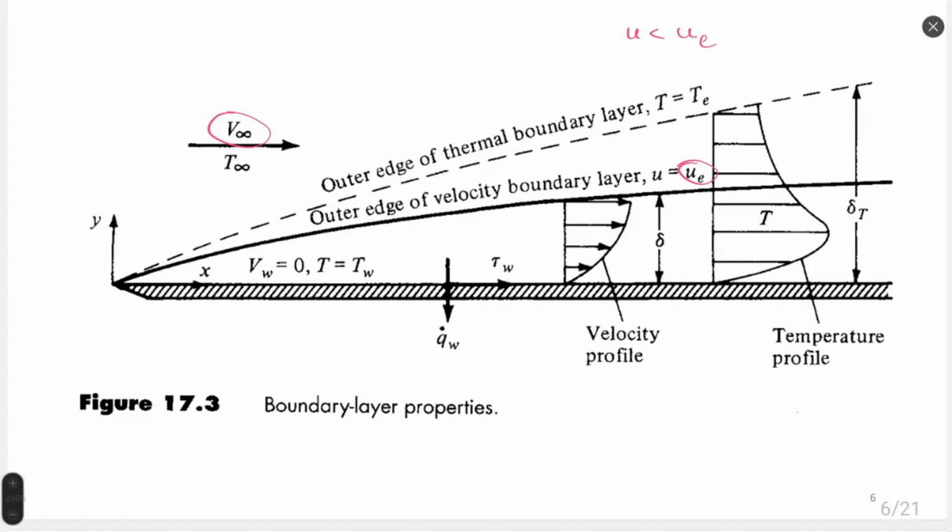In real application, it is not always possible to make such a rigid comparison, so we have some tolerance, usually from 1 to 5%. We can say that if our velocity at any particular point inside the boundary layer is equal to 0.95 to 0.99 of external velocity, we have the edge of boundary layer.